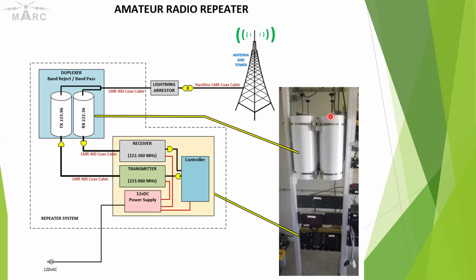You can see, we can only see 2 here, but if you look back here, you see these little knobs up here. You can see that there's 4 knobs. Each controller, if you will, is tied to a single canister. So you see 4, so that means we have 4 canisters, and that is how you tune these. So once you get it tuned on the bench and you install it, you put a spectrum analyzer on there and you tweak it to the frequency that you want to let through, okay? And most of it, again, is airspace. It's how it resonates on the inside.